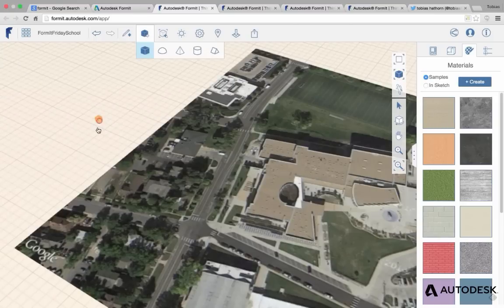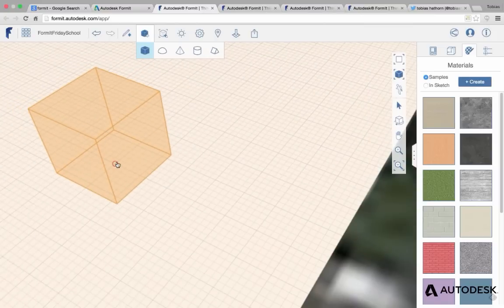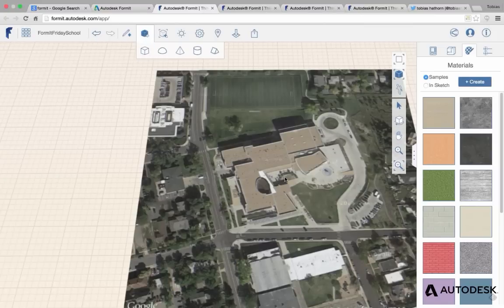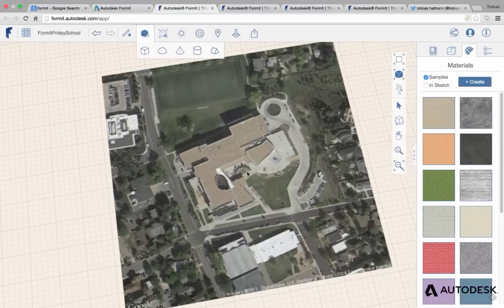normal to that grid. And that's great if your building is north, south, east, and west, but in this case it's not. So I'll show you how to rotate that grid. First step is to grab this image. So just do a double click and you'll select the image.